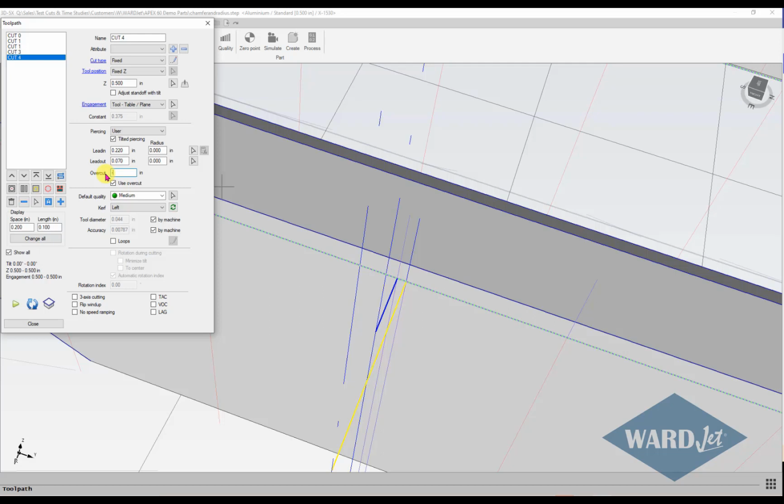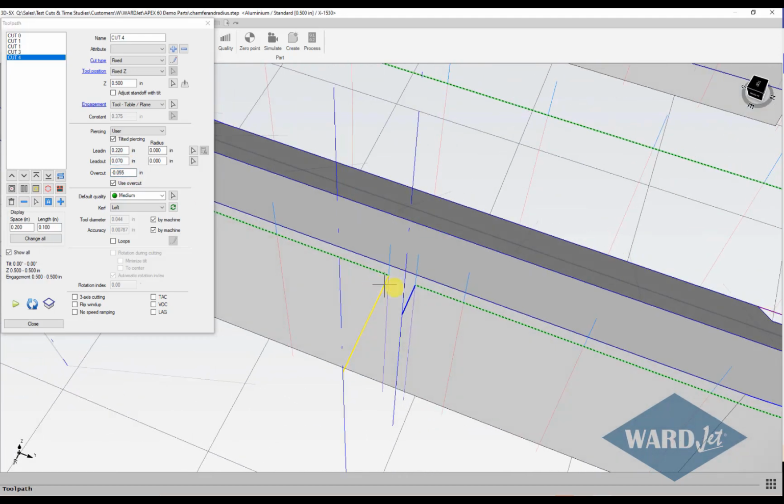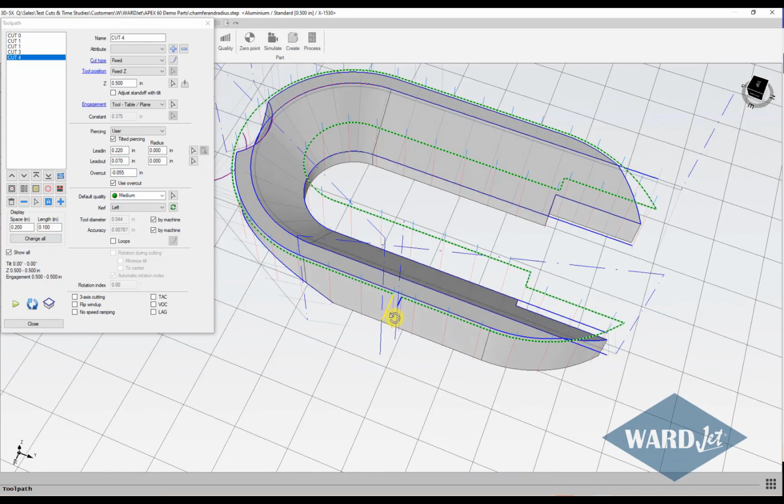and you do have to take your stream width into account. So if I wanted a 10 thousandths tab and I've got about a 45 thou stream width, then to be safe, I'm going to make this 60. So we should end up with, once we subtract off our kerf width, about a 15 to 20 thou tab there. That's a little generous. We'll make it 55. So that should be about a 10 thou tab.